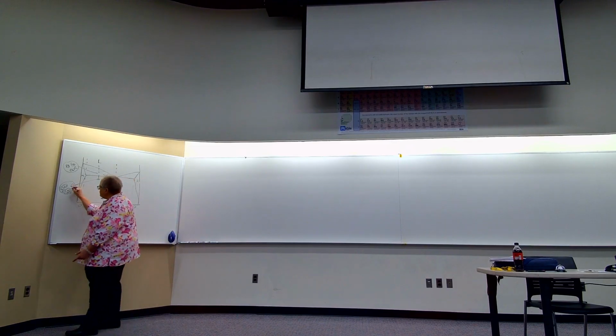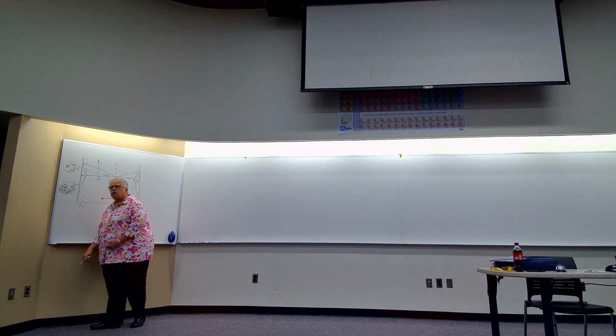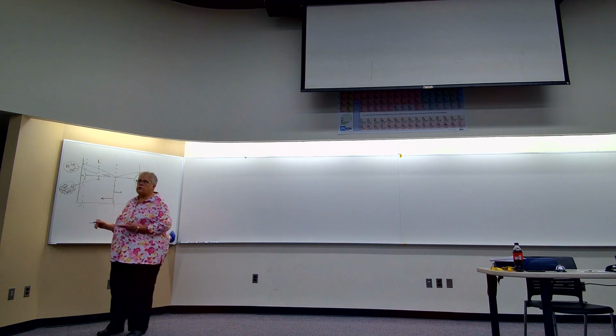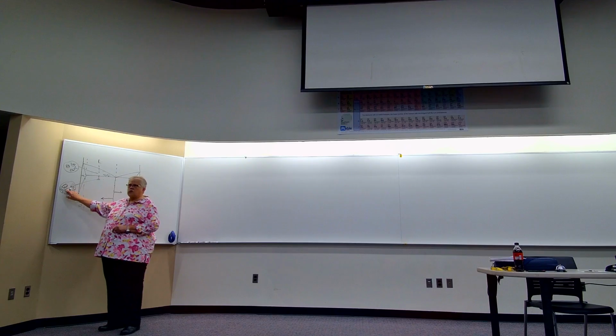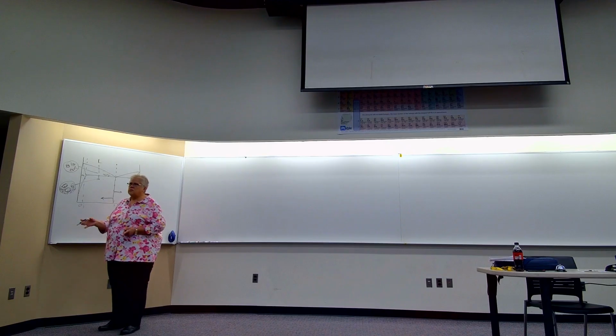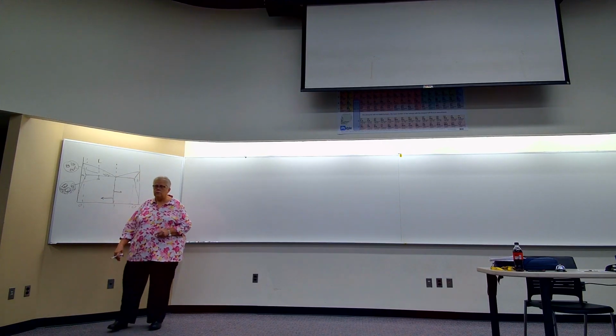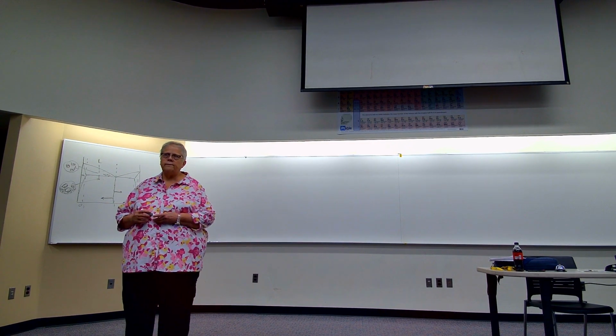So I've got these chunks of alpha, and then alpha in the eutectic. So it's kind of two ways of looking at this. I have two different phases, right? Phase diagram, alpha and beta. I also have two different structures: pro-eutectic structure and eutectic structure. So the point of asking that question is for you to look at this in two different ways, because that's what we will be doing with steel today. Does that make it clear?